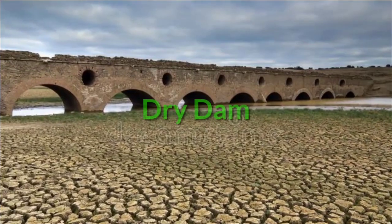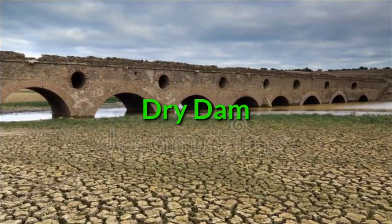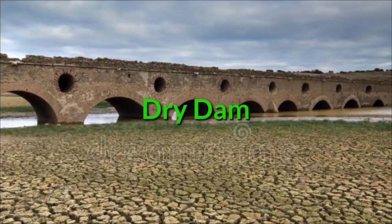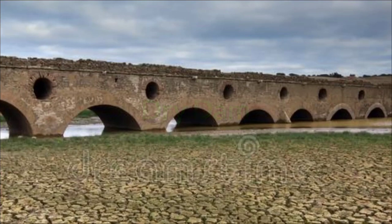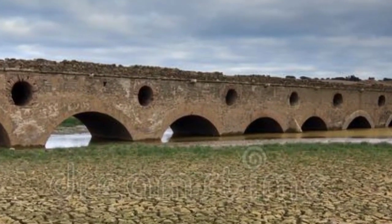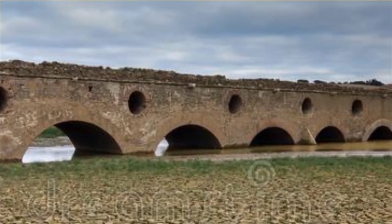Next one is the dry dam. A dry dam is also known as a flood retarding structure. It is designed to control flooding. It normally holds back no water and allows the channel to flow freely, except during periods of intense flow which would otherwise cause flooding at downstream sites.